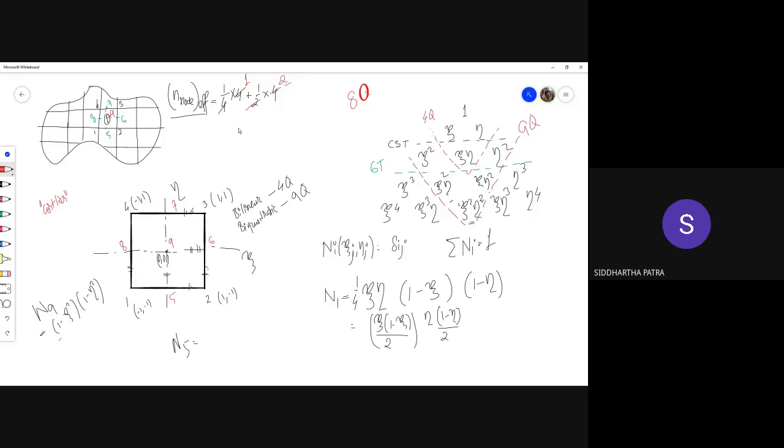So basically you need to simply add 1. I mean, in your mind, in a 9-noded quad element, what is the change in node count? Why am I bothered about node count? Because you see there are 2 degrees of freedom per node.